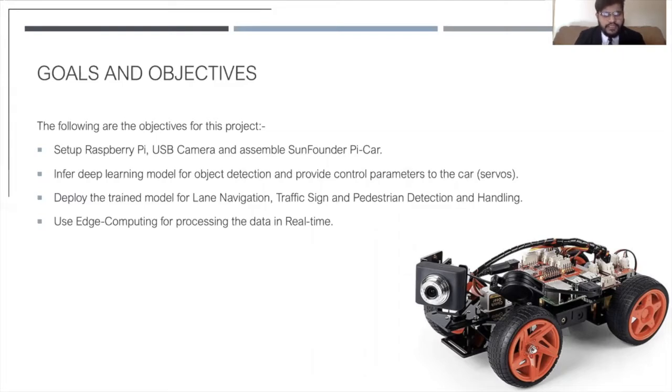But in addition, this kit comes disassembled. We have to assemble the kit, and then all the functioning of the components, the servos, have to be tested. So in my zip folder, which I have provided, I have already given code to configure these servos, because these servos cannot be configured manually. They have to be configured with the software, and they have to be at a specific angle so that they won't get damaged.